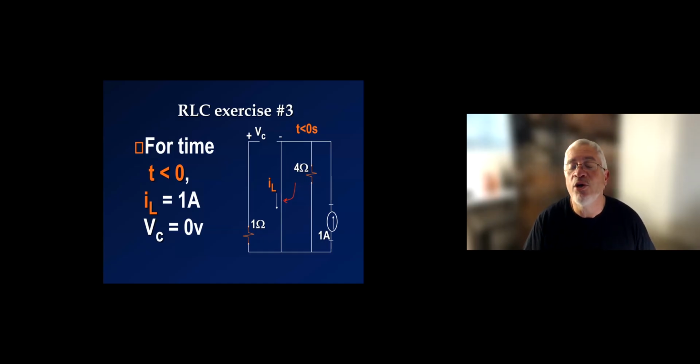The reason we need the inductor current and the capacitor voltage is because these are related to the energy in those elements. The energy in those elements is really where the initial conditions come from. So no matter what you're being asked in these circuits, you always need to calculate the capacitor voltage and the inductor current. Of course, that's if you're dealing with second order circuit. If you're dealing with first order, one or the other.